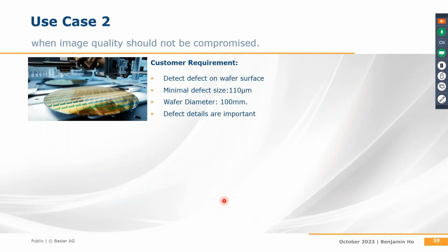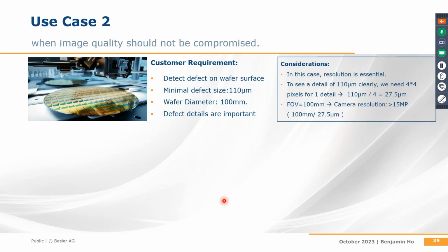Next case, the customer wants to detect a defect on the wafer surface. The minimum defect size is 110 micrometer. The wafer diameter is 100 mm. In this use case, resolution is essential.